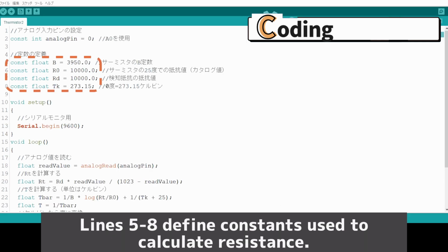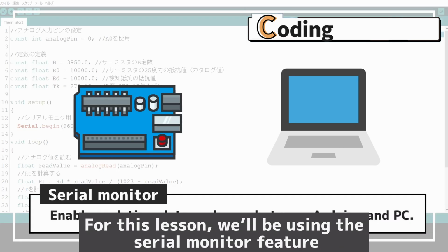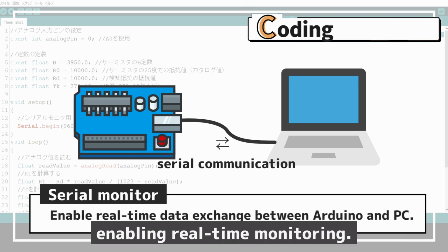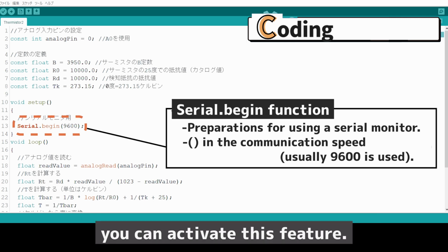Lines 5 to 8 define constants used to calculate resistance. We're using the float data type here because we're dealing with decimal points and division. For this lesson, we'll be using the serial monitor feature to observe the changes in values. This feature allows Arduino and your computer to communicate data via serial, enabling real-time monitoring. By using the Serial.begin function inside the setup function, you can activate this feature.